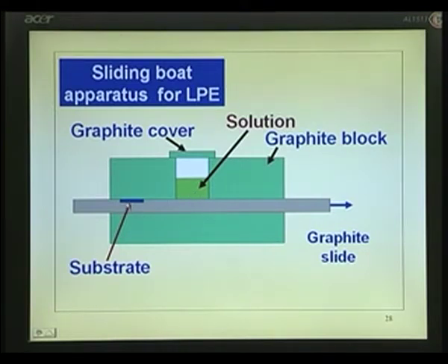Now, this is actually a substrate. That could be the semi-insulating substrate which you have put. So, on that slider you have a depression where you can put the wafer. Okay, you get the idea. So, this is a depression in which you put the wafer. I am showing a small one, but maybe 1 inch, 2 inch or 3 inch. Put it there, heat this up to the required temperature.